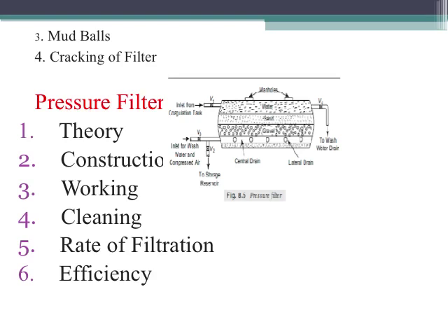Next is about the pressure filters. They are just like small rapid gravity filters which are placed in closed vessels, and the water is treated by passing through them under high pressure. Since water is forced into such filters at a pressure greater than atmospheric pressure, it is necessary that these filters are located in airtight vessels.